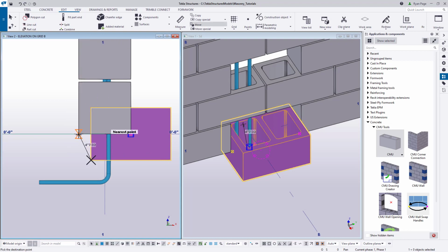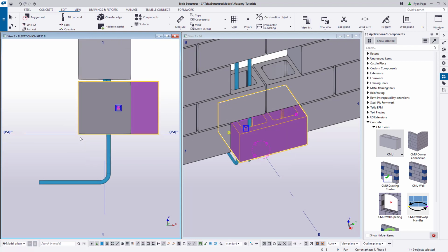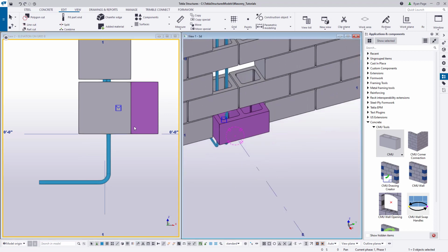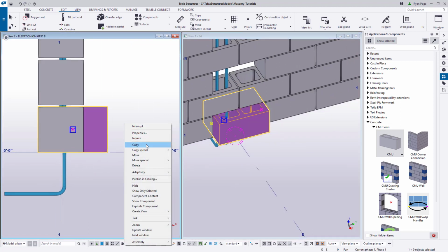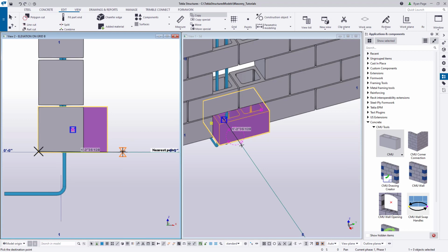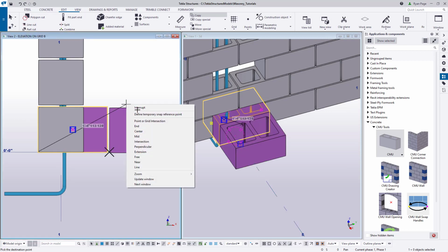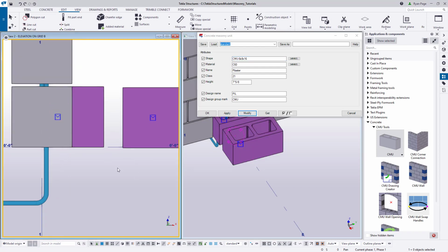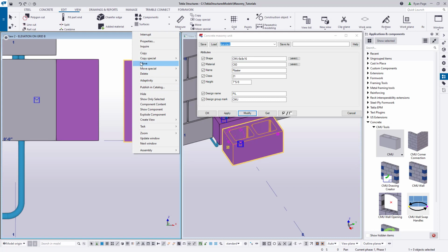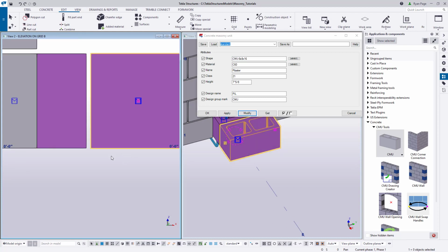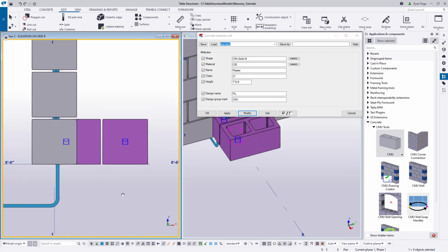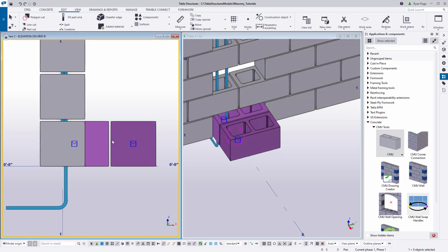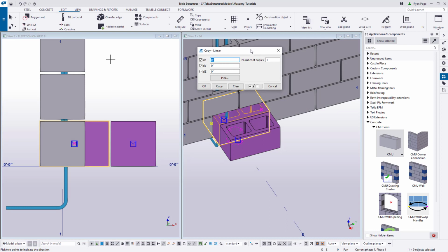After we replace the 8-inch block with the 12-inch one, we will need to add another 8-inch block to the right of that as shown on screen. We can just copy our 12-inch block directly to the right and then change its size to an 8-inch unit, and make sure that our gap remains at 3/8 of an inch. On the second course, we are going to place a 12-inch block against the two 8-inch blocks of our wall, so that it is centered at the mortar gap.